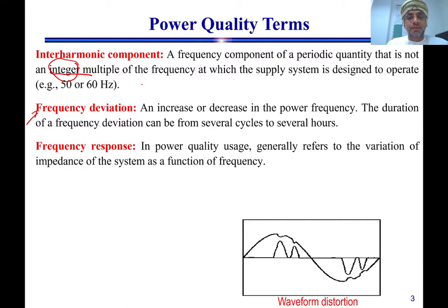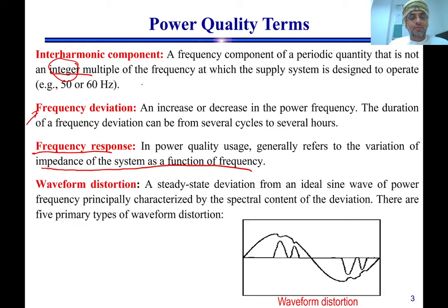Frequency response in power quality generally refers to the variation of the impedance of the system as a function of the frequency. So when we say calculate the frequency response, we mean we're going to find the relationship between the system impedance as a function of the frequency. And again, we're going to solve some problems, and we're going to do the simulation by using MATLAB to find the frequency